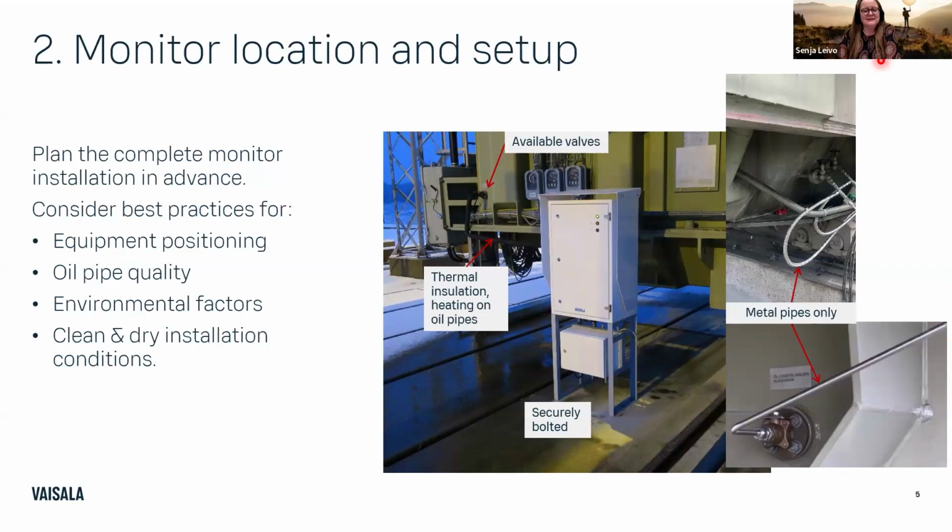Okay, so let's move on. Once you have decided that these transformers will have the monitoring, the next thing to do is to really do proper planning. Look at the site, consider everything there. How to access the oil, how to get the oil to the monitor, where to put the monitor, and so on. Really do proper planning, because it's always easier to do the planning on paper than there on site once you have all the bits and pieces